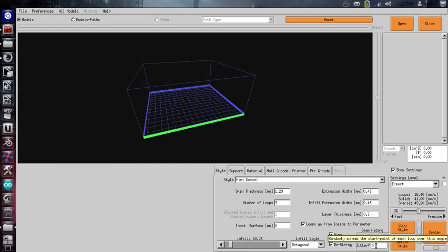Jitter, this is a setting that you can set from 0 to 360, and as you can probably tell, 360 is in degrees, and it will randomly select a start location along that set amount of degrees that you set theta to be. So a good rule of thumb is just to leave it at 0. If you don't, then you end up with nubs surrounding your model. If you have a circular model and you don't mind nubs and think of them as artistic, then yeah, go ahead and turn it on 360. It'll look nice.